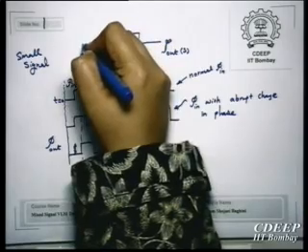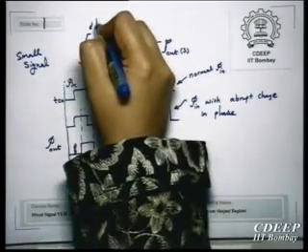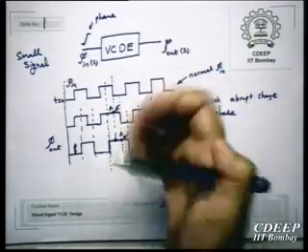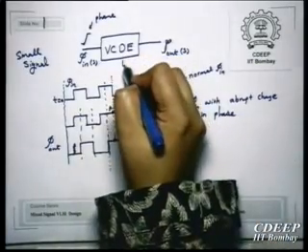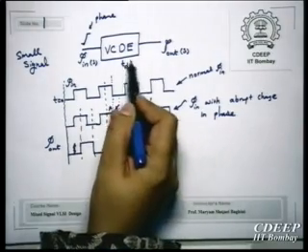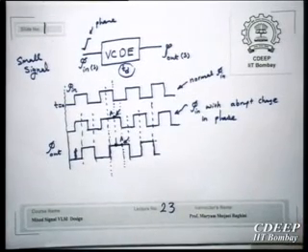Therefore, if I have an abrupt change in the phase, so this is phase, not amplitude. This is phase. This phase doesn't reach the output. Output doesn't see it unless there is a time delay, and then output will follow it. Effectively, even for phase, a variation or change in the phase will have this latency. And that's why effectively it is not able to respond instantaneously. Therefore, phase also has its own delay.